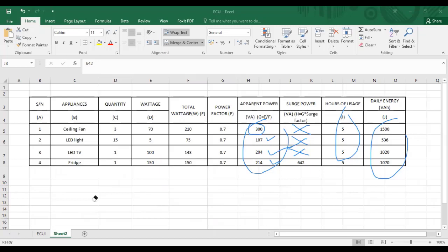Most times you can have some surge as far as 5 times the normal power, or the continuous power of the fridge. So if the fridge is 200 watt, that means the surge power can be 5 times. But now we are having more energy efficient devices and the surge also is being looked into. Okay, so I believe I've explained that.